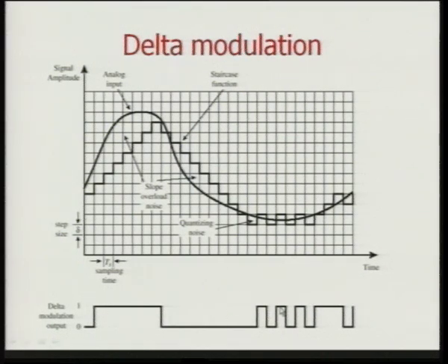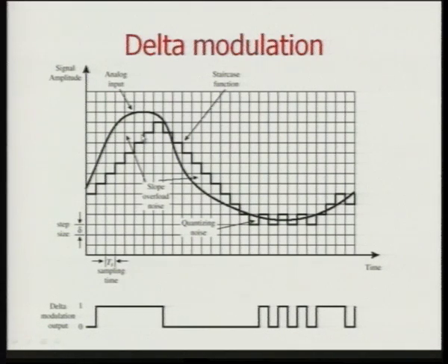When this digital data is sent out, I have to reconstruct my original signal from this digital data that I have. So, whenever I see a 1, all I need to do is increase the step value. Again there is a 1 value, so my step value increases. Again another 1, so it increases. So, this 1, 1, 1 here, the different steps that you get will be the signal that you get when you reconstruct the digital data that is sent.